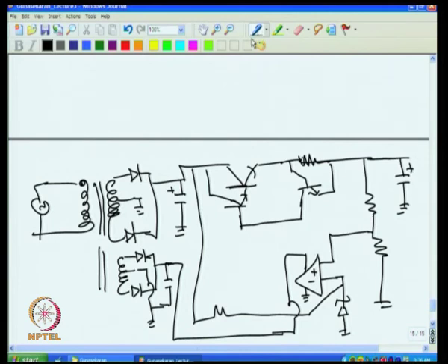Now, what I do, I will connect this fellow, the output. Suppose I connect directly to the output like what we had done earlier, it will not work, because the supply voltage we have is only 20 volt, and this cannot go more than 20. If the supply is 20, then this cannot go more than 20. So, if I connect this here, then this output can go only to 20, not more. If this itself is 20, then you have 20 here and 19.4 here and 18.8 only maximum possible, but we want 100 volt. So, we cannot connect this directly to get high voltage output here.